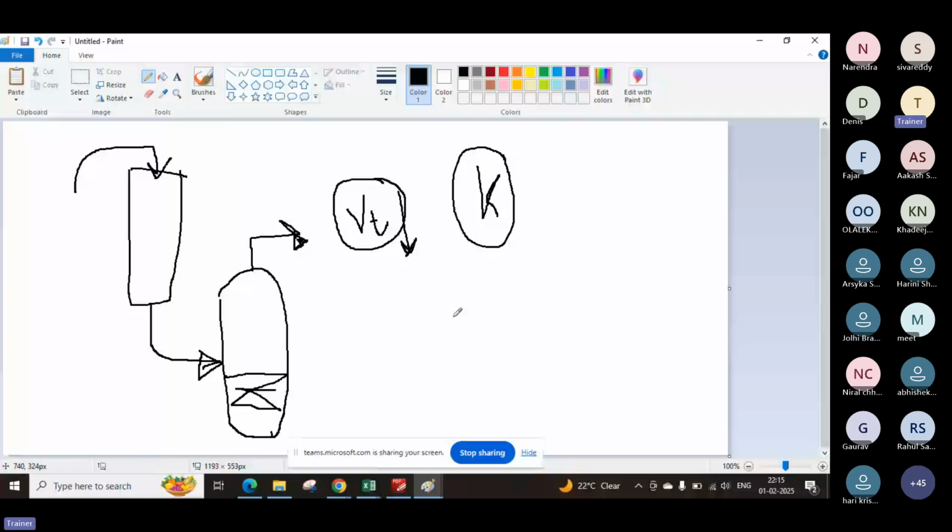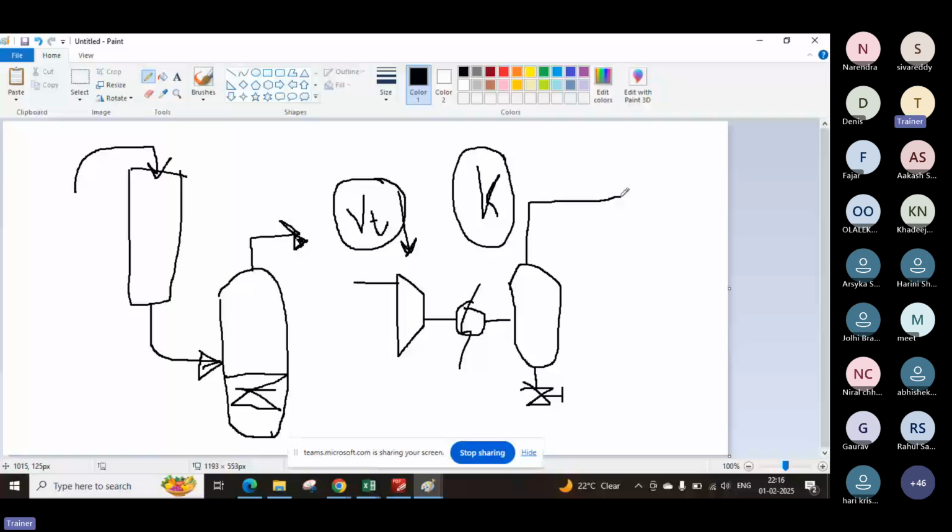If you have seen air compressors in your plant, that is having a cooler and air compressor, I'm talking about air, then this is the separator, and this generally has a manual valve. Or even if this air is coming from OSBL, outside battery limit, to inside battery limit, generally companies provide a separator at this point with a shutdown valve.